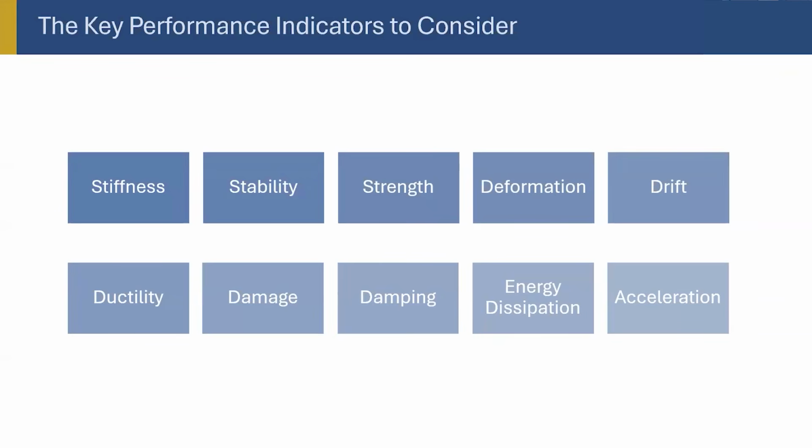Damping is going to be very important because for dynamic response, damping is extremely critical. So we have to make sure that structures have enough damping. If not enough damping, we add damping or we remove damping. Damping changes over time. Then damping changes over the loading history and so on. So damping is not a constant number. So we have to watch for damping very carefully.